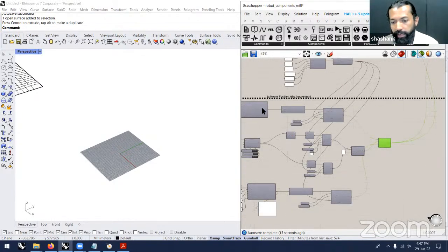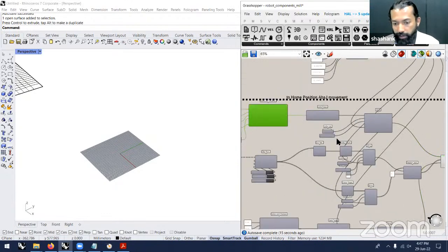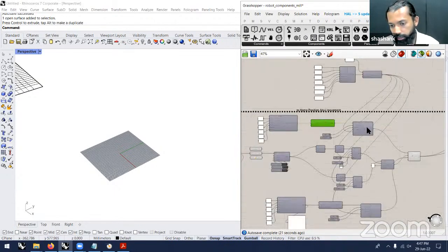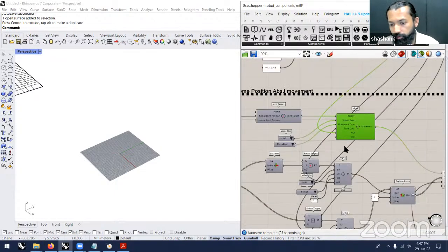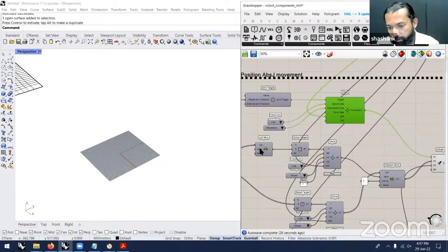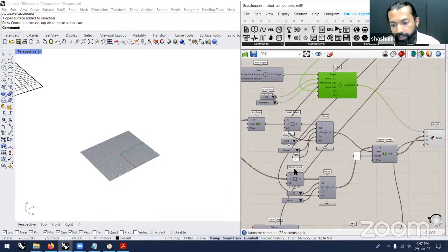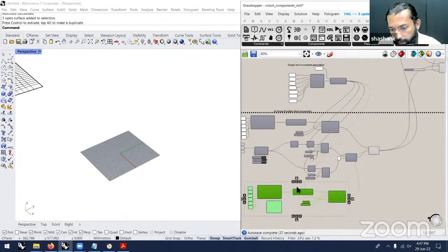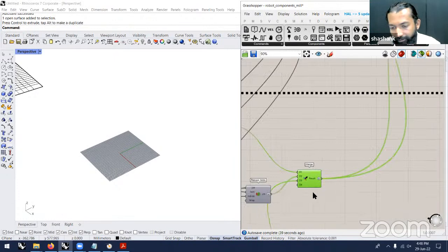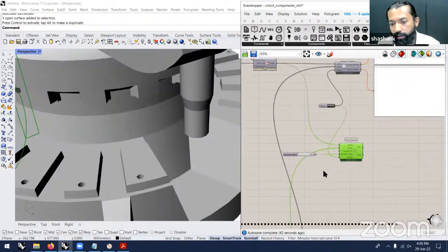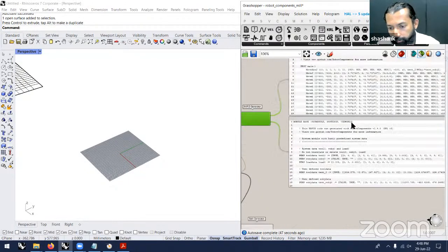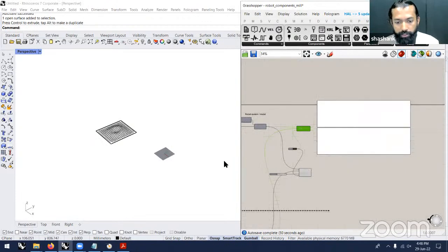together. So here, as we discussed yesterday, I've first given the absolute J value to the home position. I've given it as a joint target and fed it into the move component, and the next one is the first move, which is a move J, and then I have the whole set of move L points going into this, and finally it is going back to home again. So I've merged all of this, flattened it, and sent it back into the path planner and this component. So now I have this created. I'm just going to see how the simulation works.